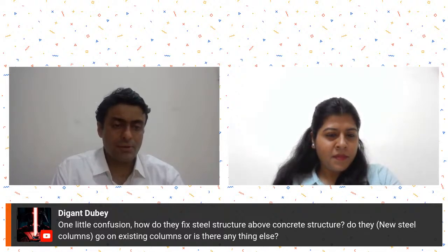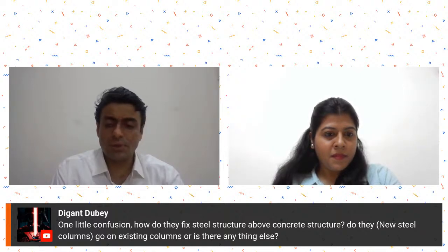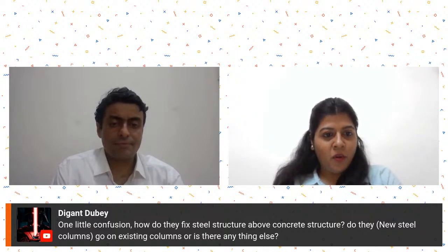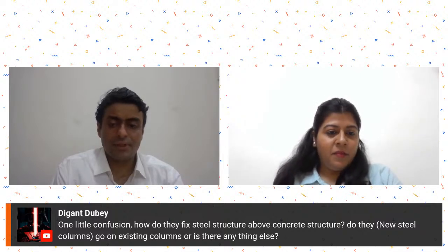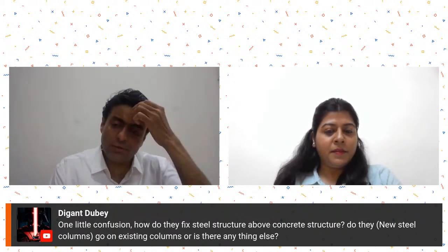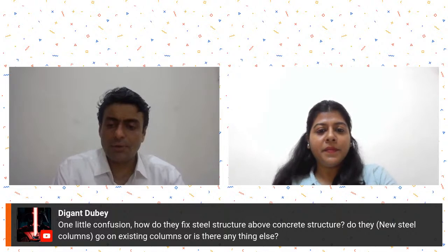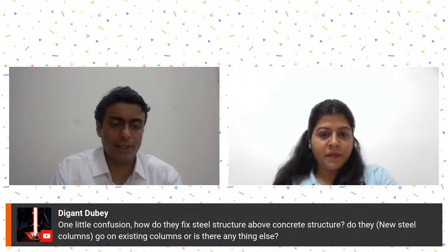Do they go on existing columns or is there anything else? I think he wants to know how you fix the steel columns to the RCC structure below. So there's a base plate, there's a proper connection design for that. I think he wants to know whether you... I mean, it's a generalized question, so let me answer. He's saying, do you put it on a base plate? That's what I understand, or you directly embed the steel column inside the RCC pedestal.